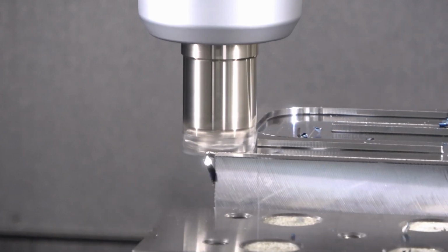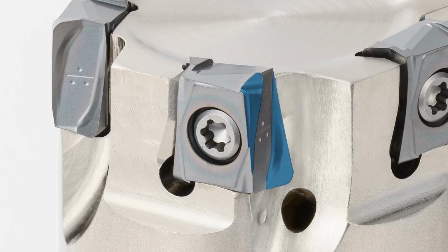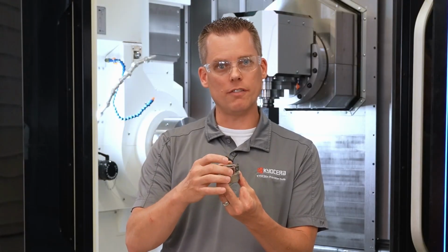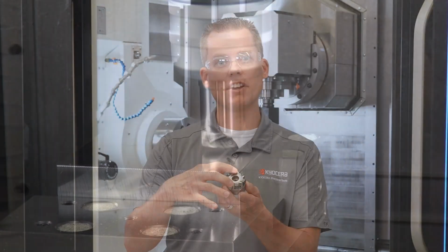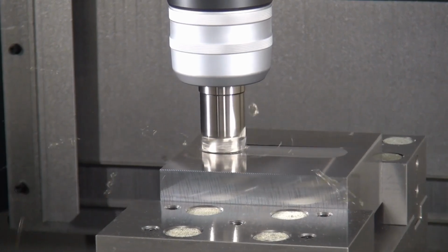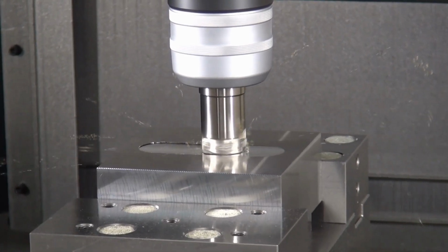They're extremely versatile. The cutter that I have in my hands right now is what's called a tangential cutter. These typically have 4 cutting edges per insert. They offer a very robust seating surface. They're very strong. They leave a very nice sidewall finish. They leave a very nice face finish. And this one in particular, our new MA90, does have the capability of ramping. So you can enter into a pocket, enlarge a hole, or slot without an entry hole.